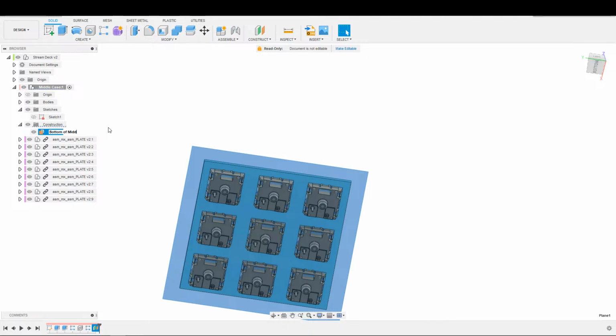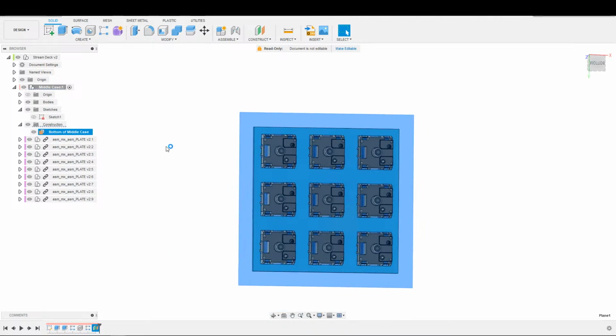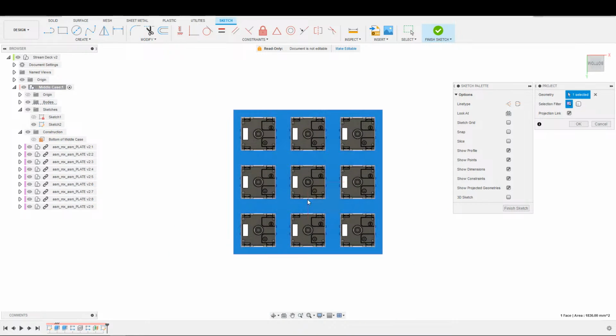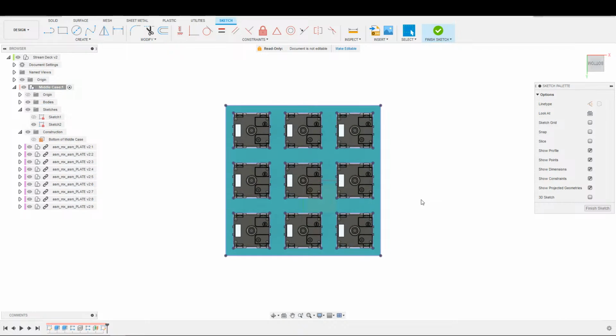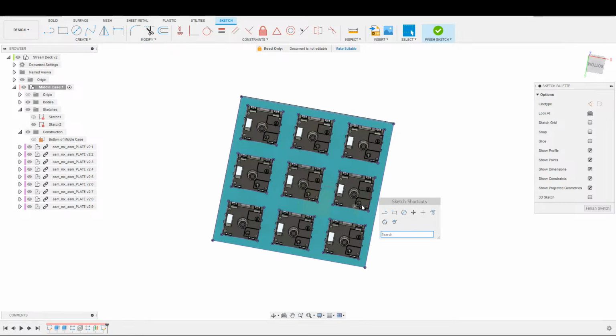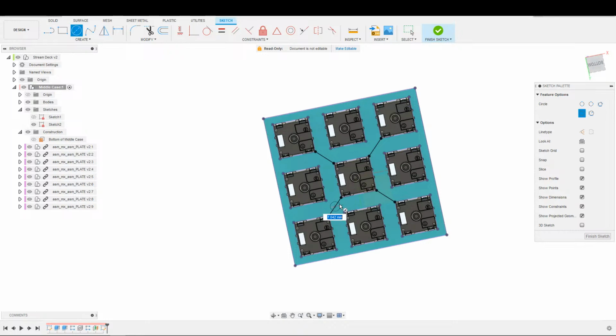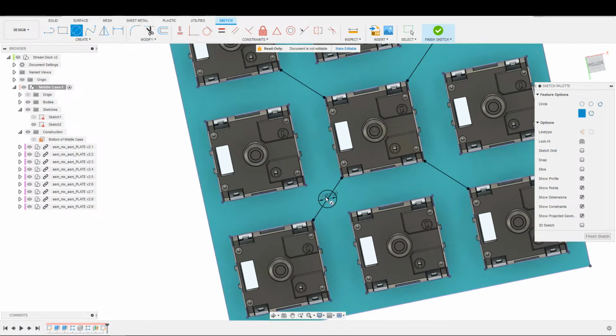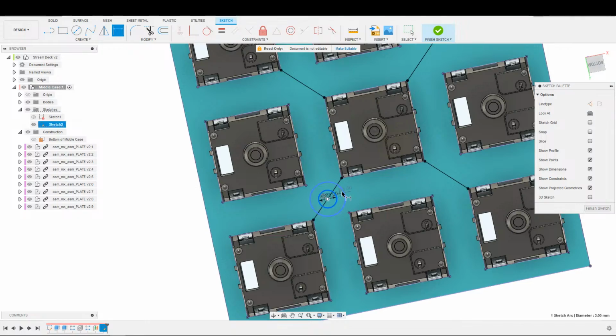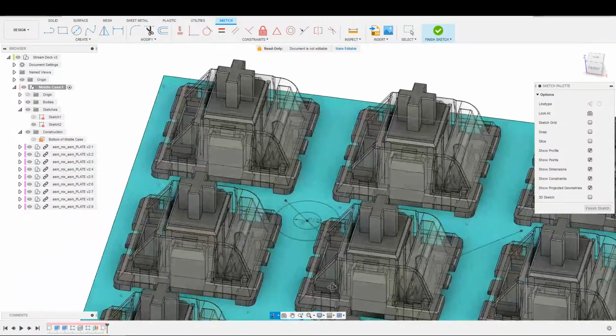Bottom of middle case. Draw the sketch, and now I'm just going to throw some standoffs in here to attach to the bottom case. There's a couple ways we could attach this, right? So back to our good old friends, the bolts. We could run bolts through it and screw it down to the bottom. Let's see what that looks like. So M3s, let's say. And then we want 2mm walls around the M3s. So there's that. So we do have clearance right there.